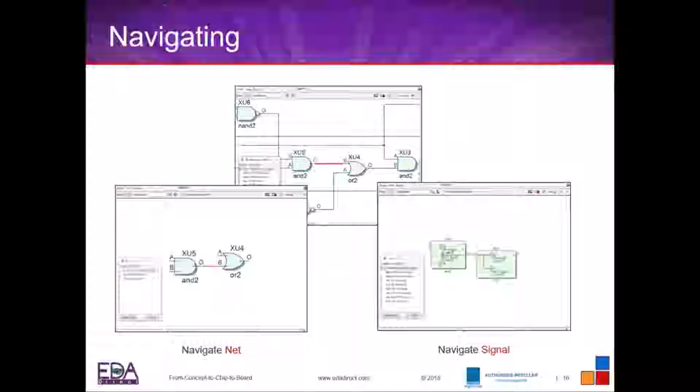As your designs get rather large, we have this methodology called divide and conquer. Typically you're only interested in looking at a particular branch in your circuit, not the whole circuit. To speed up the analysis of schematic rendering, you copy that object into what we call the cone window. Then you can double click on the inputs and the outputs, and we generate a netlist appropriately.